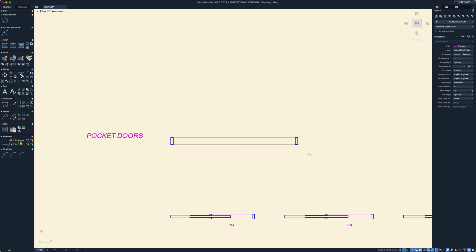Okay, now the way a garage door works is it slides up and it sort of rolls into the room, and in its open position, like I said, it curves up, goes up, curves into the room, and it will be on a track just below the ceiling. So we have to make sure that we have enough depth in our room to allow us to open that door. Now a standard garage door is going to be around 2,140 millimeters.